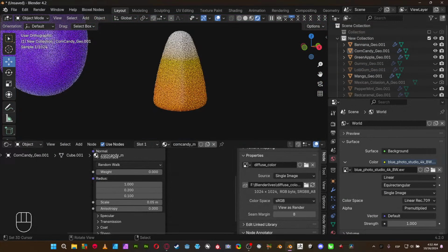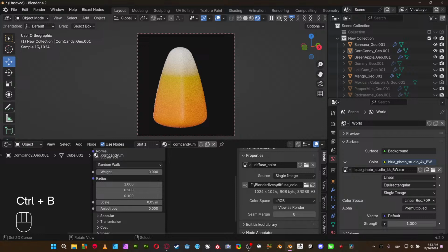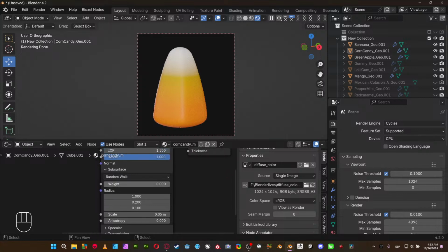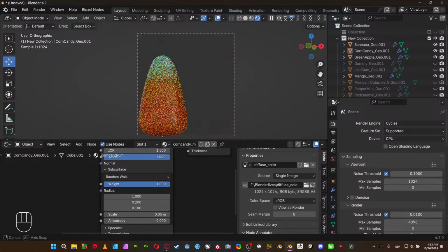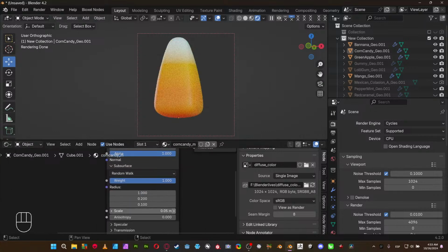And I'm gonna call this guy. Yep. Let's just render just this small guy in here. I don't need to see the other guys. So first of all, if we're gonna work just in Cycles, the values in here are gonna change drastically. So let's just apply the weight in here. As you can see, the subsurface scattering is already working. Let's just add a little bit more power just in order to show you how it looks. 0.1, and there you go.